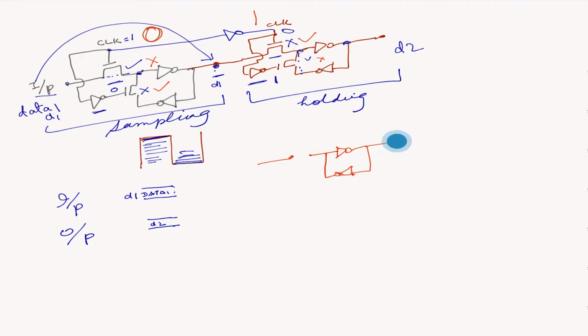This is on. And in the next stage, this is on. This is happening now. The first circuit, which was sampling, now it's keeping the value, whatever value we stored before here. It's inverted and then inverted again. So that means this node maintains its previous value. However, when clock is 0, now this second stage is letting whatever is here go to the output.